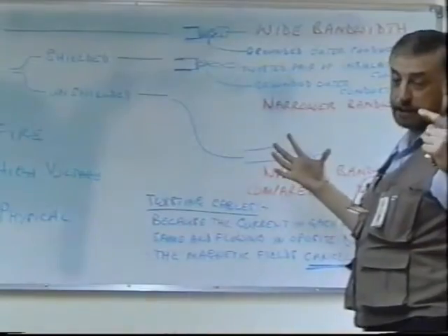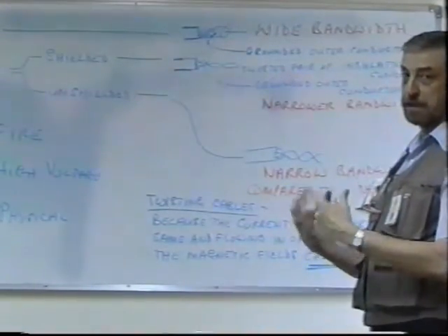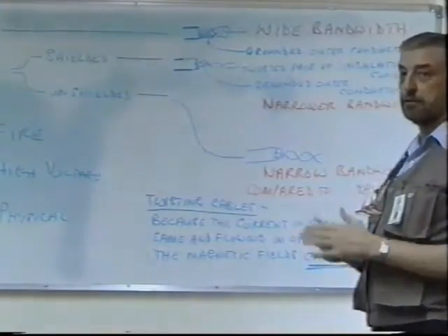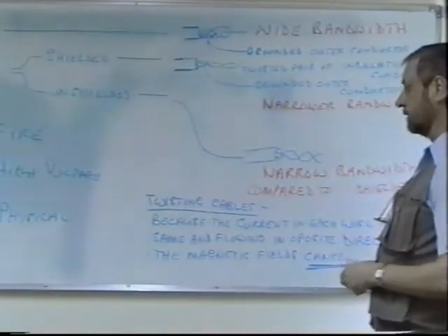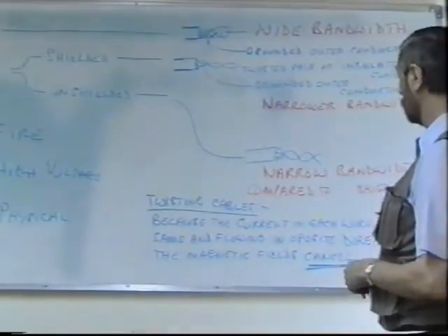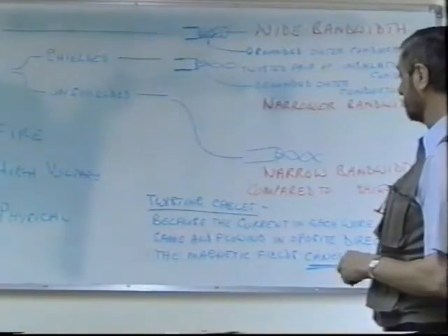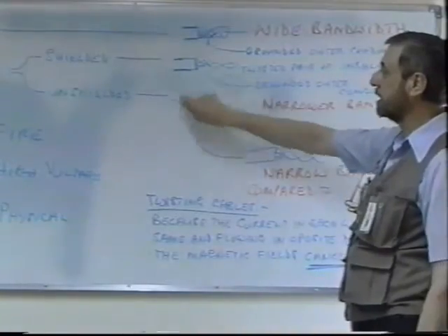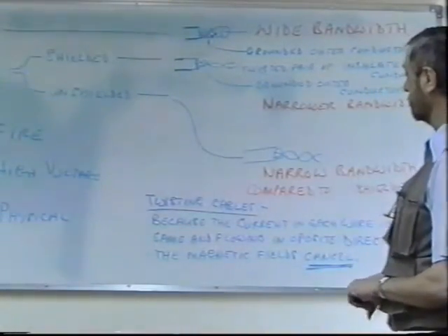And it's the same with magnetic fields from the outside. They'll cancel in the cabling, so you won't get as much noise, and you can afford a wider bandwidth of signal. This is the reason why we twist the cabling together. And indeed, for both the shielded and unshielded, you have twisted cabling.